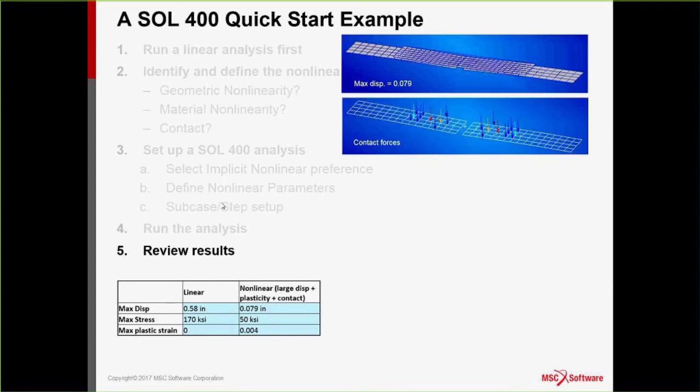Now let's look at contact. There is certainly contact, so I'm just plotting some of the contact vectors. In this problem, there wasn't that much contact force. I think the largest contact force is about 20, 30 pounds, right? Because we're not applying a load out of plane. We're really applying a load in plane. But contact is still actually important because we are picking up contact forces here.